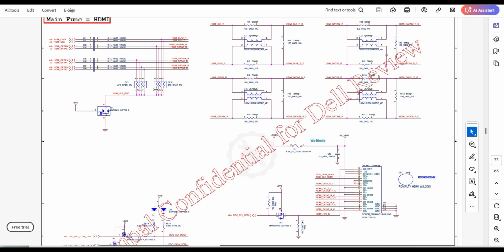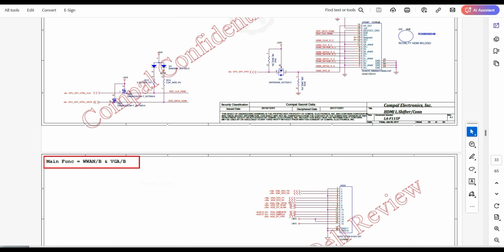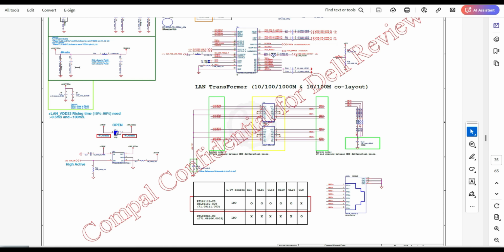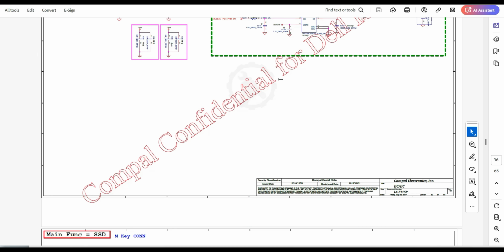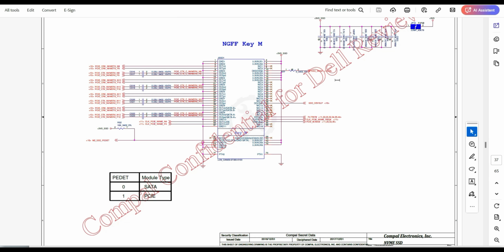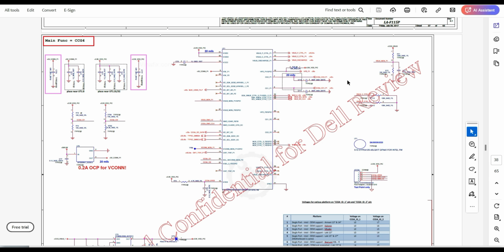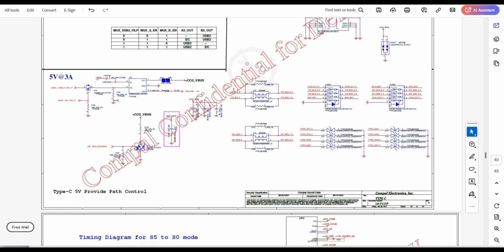Or here is the network resistor. Here is the series. After this diode, whatever voltage is there will cross this 2.2 resistor, 0402 size. 04 is the length and 02 is the width. See, here also resistors. Okay, like this, in the same condition you will get the voltage divider or pull up or pull down. Just a minute. See, I'll go a little bit fast.